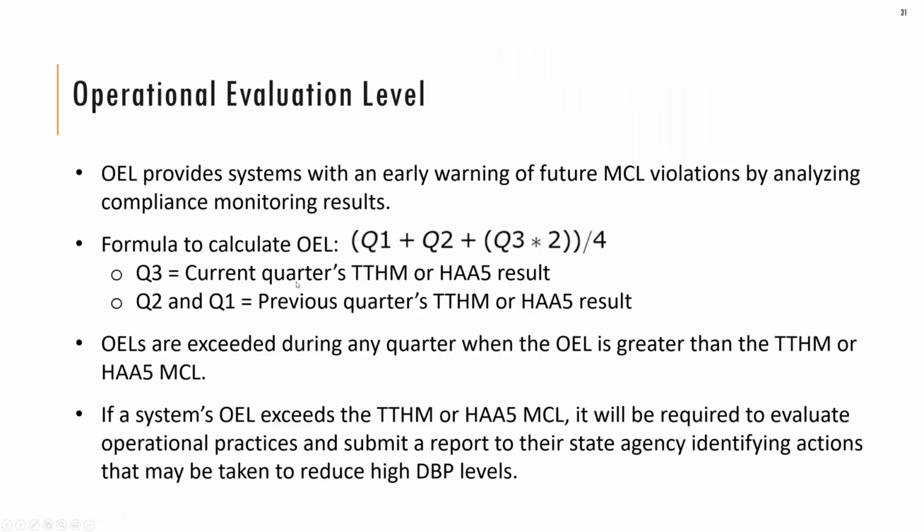So now that water systems have collected their water samples and got their results back from the laboratory, they are required to use that analysis data to calculate the operational evaluation level. This is still required of every water system: complete the OEL. It's a new requirement under the Stage 2 DBPR, and it's designed for water systems that are on quarterly frequency. It provides a system with an early warning